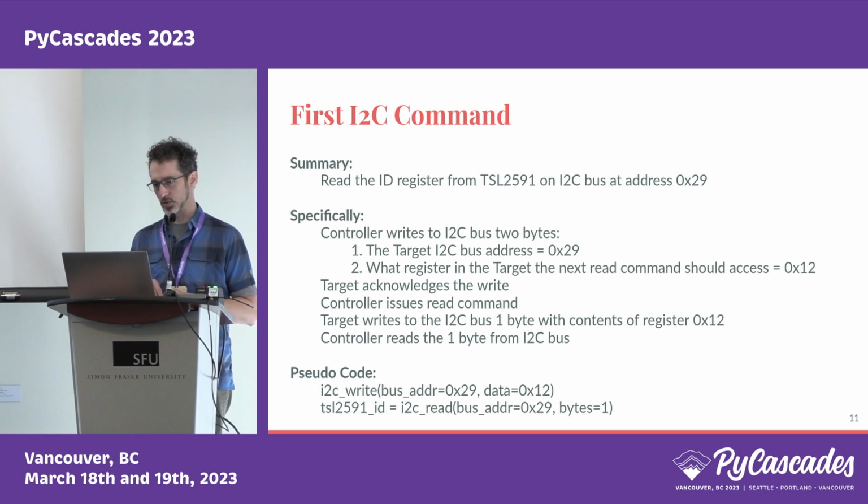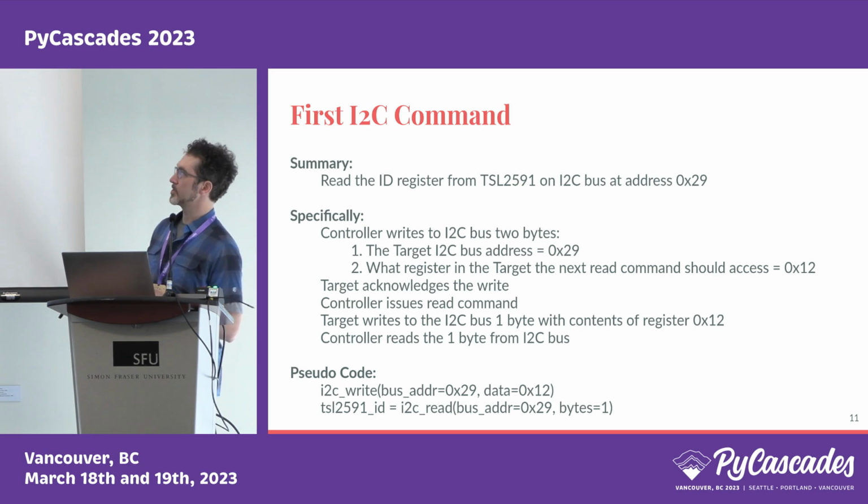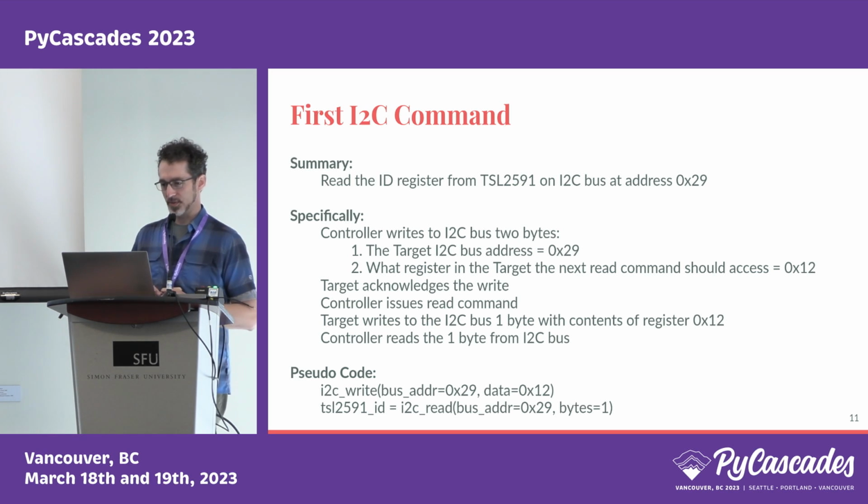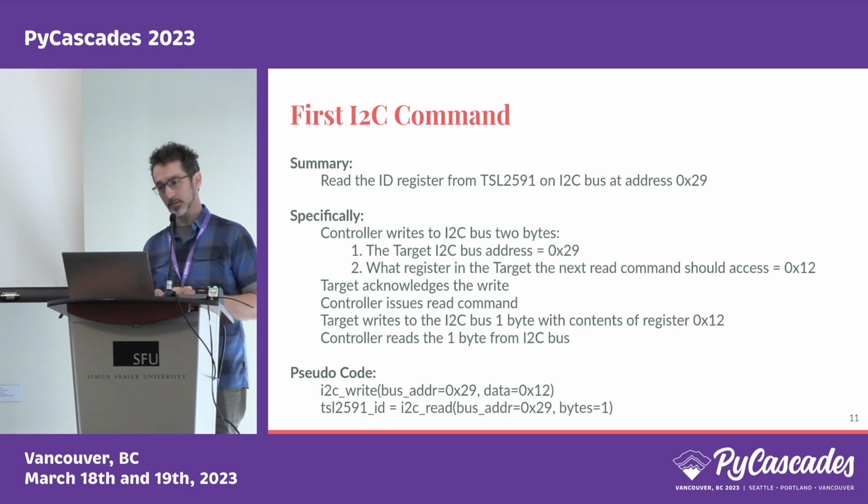So our goal is to, on the bus, I should back up a step. I am going to write to read a specific register. So looking at the datasheet, I was looking for a read-only register. And this is part of, I do this regularly with devices. I go look for something that is a read-only register that never changes. And manufacturers include these so that you can do exactly this. During development, I just need to get a constant that I know is supposed to be an exact number, and I know I'm reading things correctly. In this case, it's the identification number, which should be hexadecimal 50.